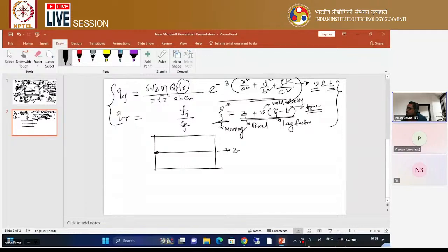What happens throughout the entire plate, this is a plate. Throughout the plate thickness, you can get a bead which is more or less uniform in nature throughout the entire region. What I'm telling, understand? Due to this high laser intensity that you know very well. So that's why this heat source model will be different.